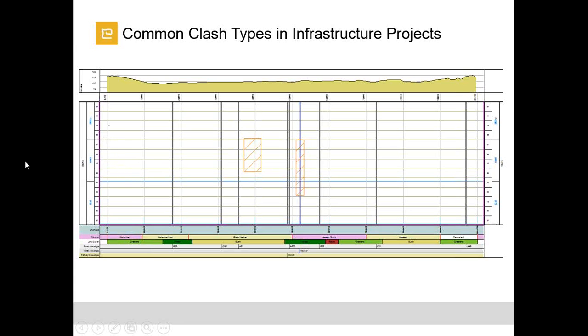So we need to take into account these two pieces of information, also these intersections, and we should plan our work. So let's say that our first activity is coming. We say that we are going to start from the first week of March, and we are moving to the right side. But the system is now indicating there is a clash, because we are not allowed to work in this restricted area, and our first activity is actually causing a clash here.